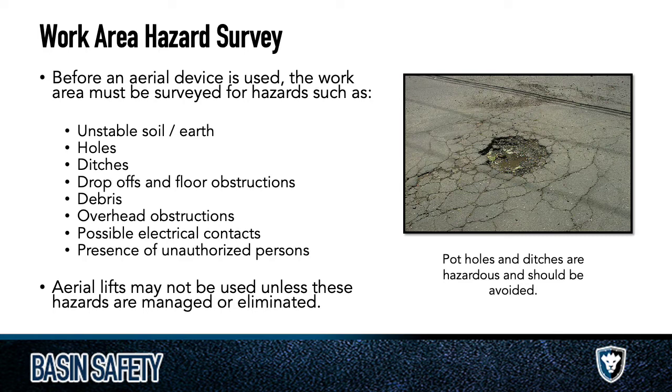Again, if you're afraid of heights, but what you should be concerned about is the work area. If you know you're going to be driving around from point A to point B to point C to point D all day, do a walk through that area first. Look for power lines. Look for unstable earth. Look for potentially earth that's been washed away and is unstable, where you're going to potentially tip that thing over when you're driving. You want to do that walk around before you go to work.